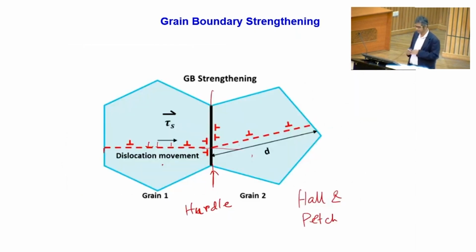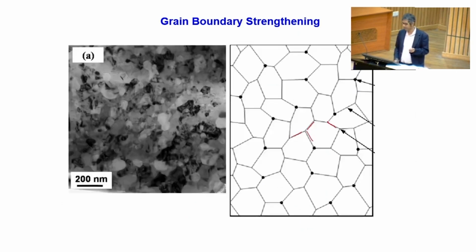So I will go back here. Okay, that's mainly because of these aspects. Grain boundaries provide an obstacle to the movement of dislocations. Remember, plasticity or plastic deformation is dictated by the generation and movement of defects. The more the movement of the defects, the more slip steps are created at the surface, and the more the plastic deformation. So if grain boundaries are not allowing the dislocations to move, the material will not deform. So the material will show higher and higher strength. Okay, that's something very unique because of the grain boundaries.